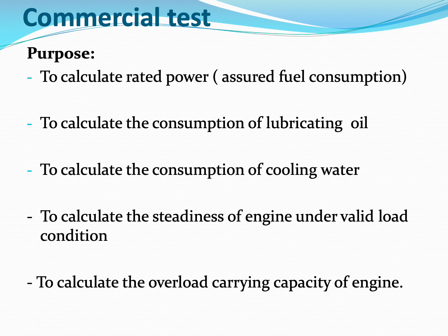Commercial test. The purposes of the commercial test are to calculate rated power, that is assured fuel consumption, that is again the mileage or performance of the engine, to calculate the consumption of lubricating oil, to calculate the consumption of cooling water and other, to calculate the steadiness of an engine under varying load condition, to calculate the overload carrying capacity of an engine. That means from the above commercial test, the manufacturer can give clear view of a performance of the vehicle.